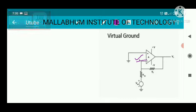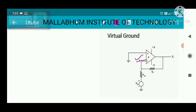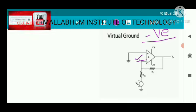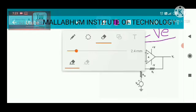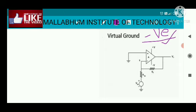So a portion of the output voltage is fed back to the negative terminal, so this is a case of negative feedback. The first point about the virtual ground is that this is the case of negative feedback. As there is negative feedback, we can apply the virtual ground concept.